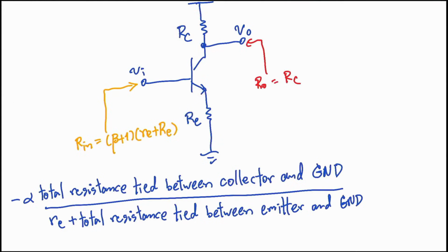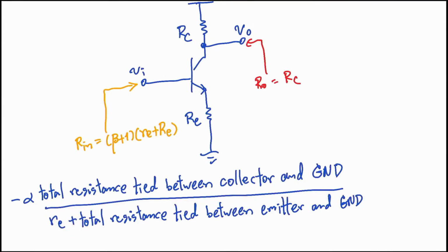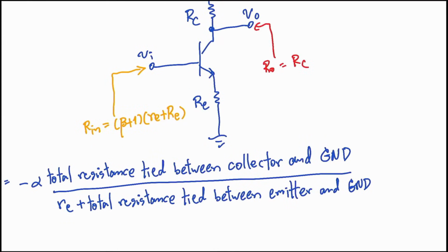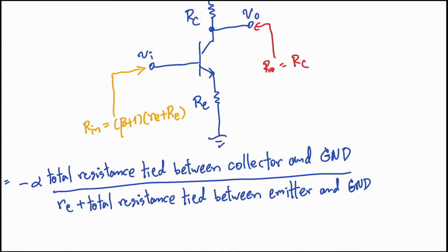If the resistance R here is significantly greater than the emitter resistance Re, then we can simplify the calculation and approximate it as RC divided by the Re located directly below the emitter, right? But of course, that is just a rough approximation. During our university studies, it is really important that we focus on remembering the correct, precise equations first before relying on these shortcuts.